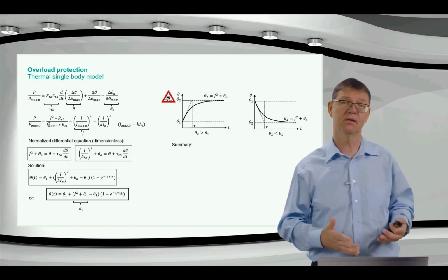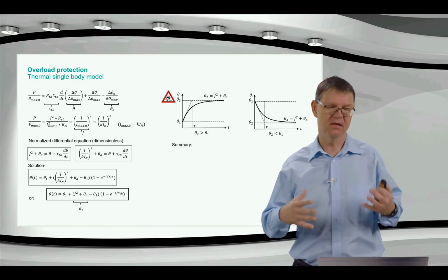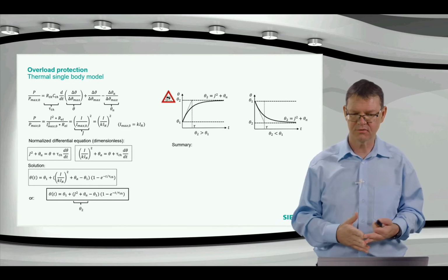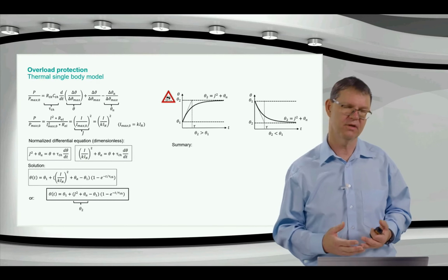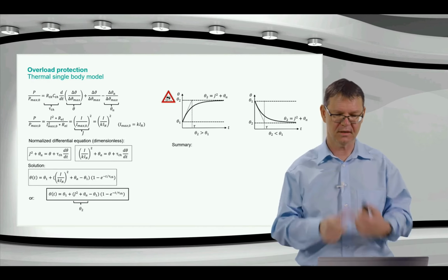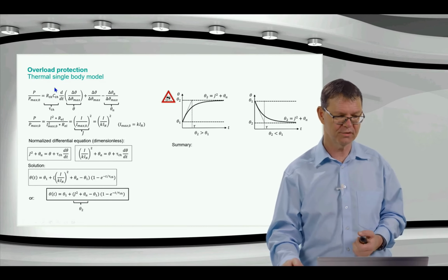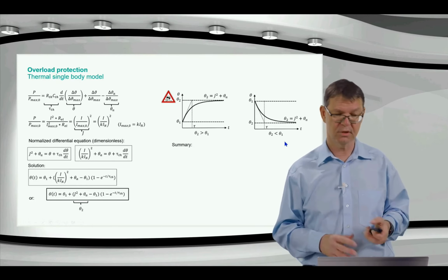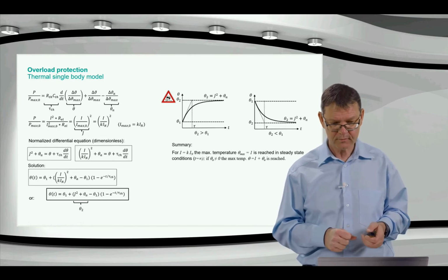So this is basically what is behind here. These calculations, as I already said, are much less complicated when it comes to the settings of that function, because we have just two settings which we consider, the k factor and this tau, the time constant, which we also get normally from the motor manufacturer, or I show you later a trick how to come to this tau.